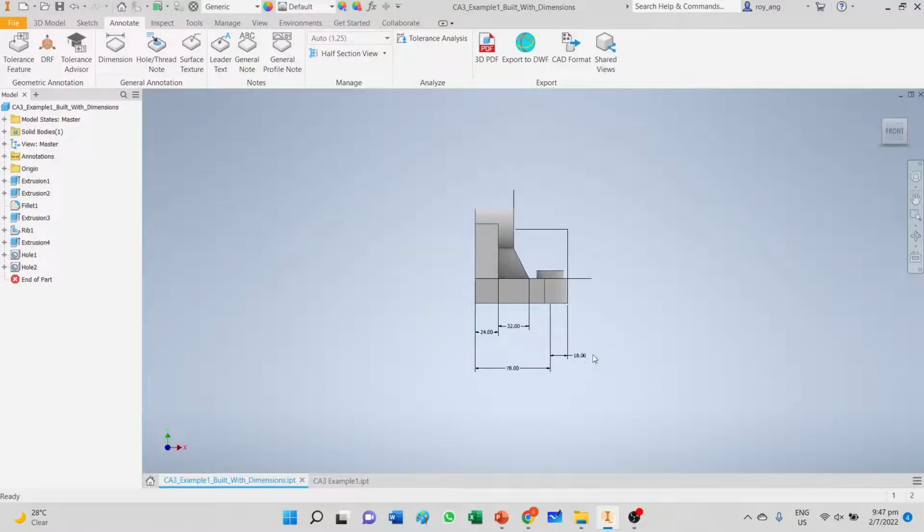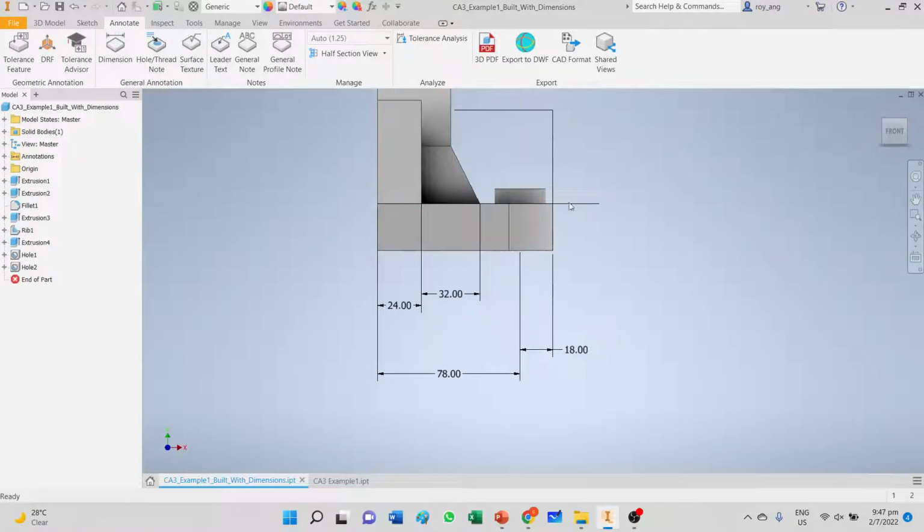However, if the design principle is, I won't fault you if you do this. I won't fault you to do this, but in the future, if you were to do something like that, it will just make the life of the machinist a little bit more difficult. That's all, because then he has to remember to take reference from another edge. Okay, so whenever you can, try to take reference from a common point, right? Like the back surface and the bottom surface.